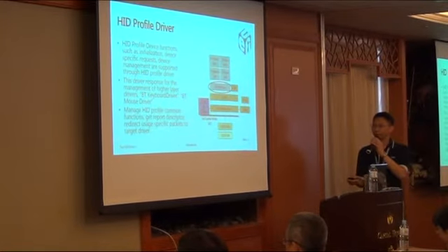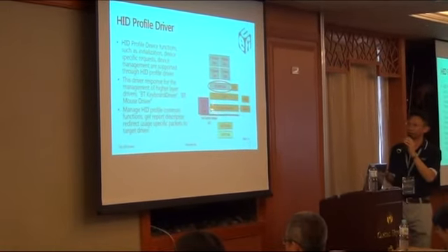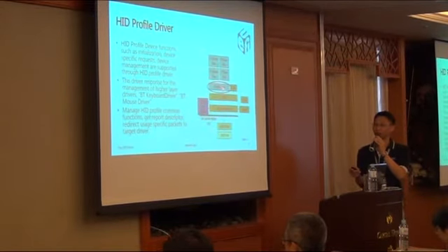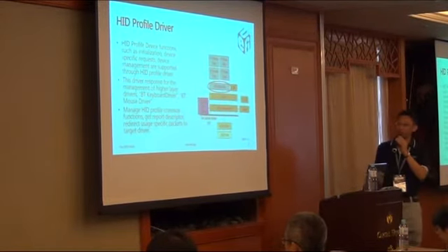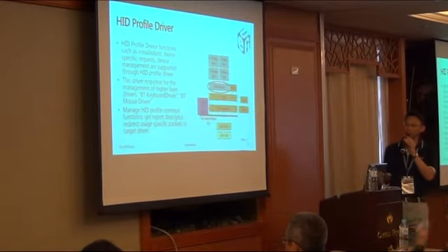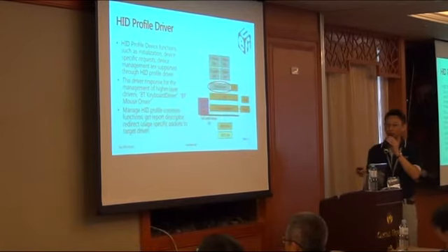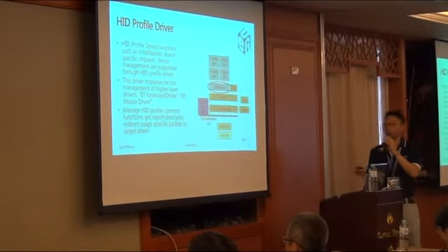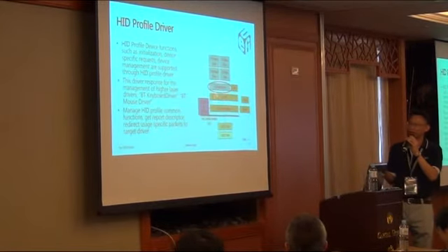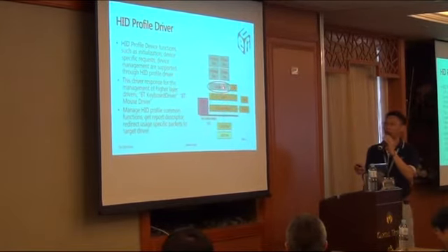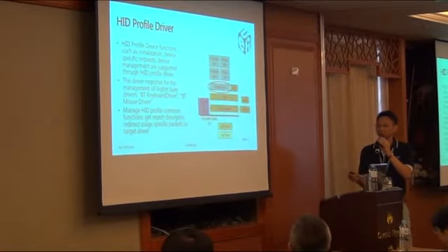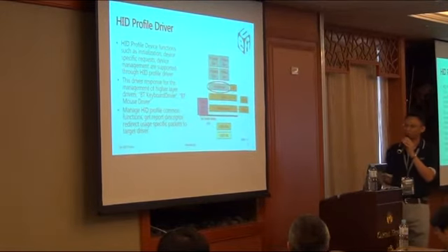Okay, so another layer is the profile driver layer. Here, there's only one profile implemented, the HID profile. What the HID profile driver does is support the HID profile requests and features. So you will initialize the HID profile, and you are responsible for checking whether the attached device supports the HID profile, then install the higher layer driver, like a keyboard or mouse, if you found a keyboard or mouse is connected.